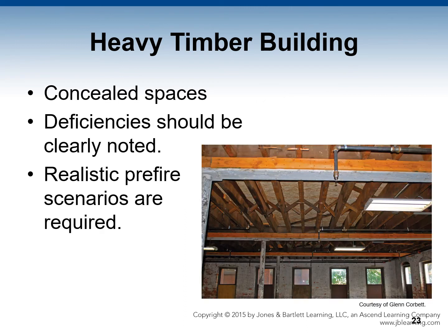With heavy timber building, concealed spaces may be created during renovation, so deficiencies should be clearly noted when inspections are done, and realistic pre-fire scenarios are required. In other words, anticipate what's likely to happen in this building during renovation when there's a good chance of a spark or something like that causing fire, and even after the building is finished being renovated. You need to know where potential problems will lie.